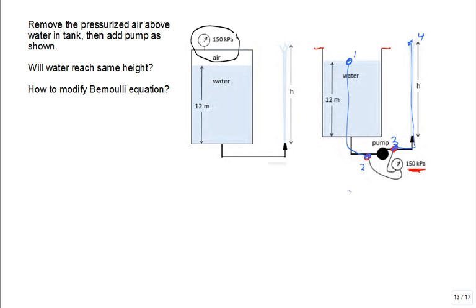So pressure at 3 is equal to the pressure at 2 plus the pressure gain across the pump of 150 kilopascal. Should I work through that math, or is it clear enough that you could do Bernoulli from 1 to 2, use this for information about the pump, and then do Bernoulli from 3 to 4, and you would calculate the same maximum? That seem reasonable?